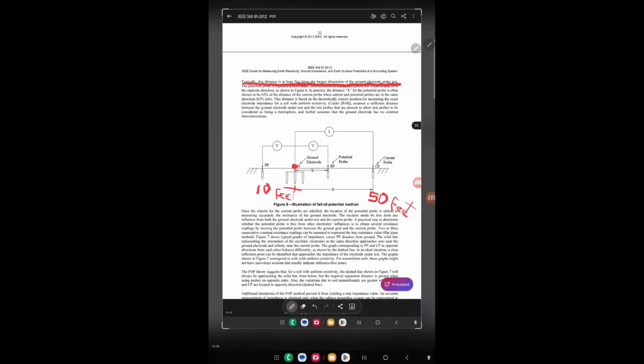But we will see it in the analysis I did of potential measurements, because remember that I did the potential measurement based on the distance. I graphed it, and I did not present it in Excel to show you the analysis. In fact, I measured 500 feet because in the field measurement, my ground bed had a length of 100 feet. And I measured the remote potential at 500 feet, and even then I realized after analyzing the data that this was not my true remote potential. We will see the analysis of the information now.